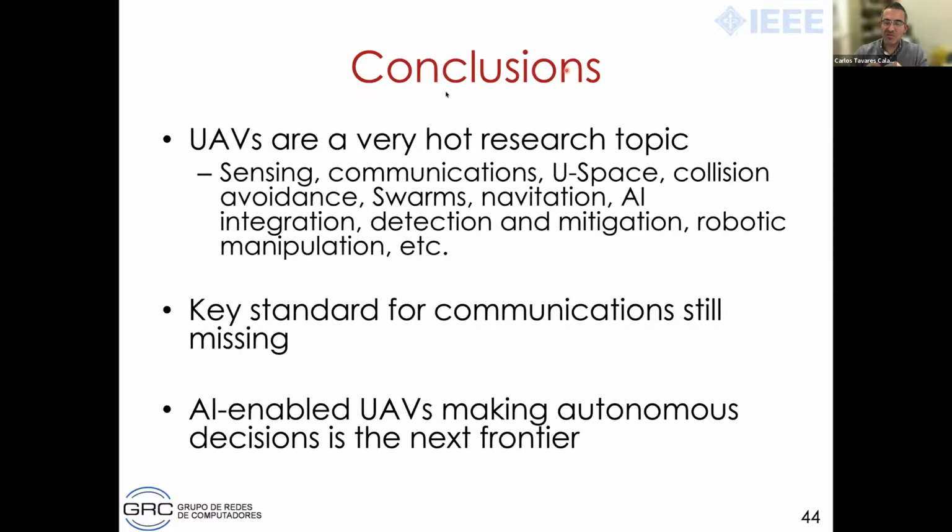Unlike commercial flights, where the airplanes have a big margin of altitudes to move around because they can fly at 8 kilometers altitude, 10 kilometers altitude, and beyond, in the case of UAVs we have a maximum altitude of 120 meters. Then the minimum altitude is often defined by building heights and other requirements. So we are already on a much thinner layer. Combine that with GPS accuracy regarding altitude, which is much worse than for XY positioning. So maybe you are actually 10 meters higher or lower than what you believe.